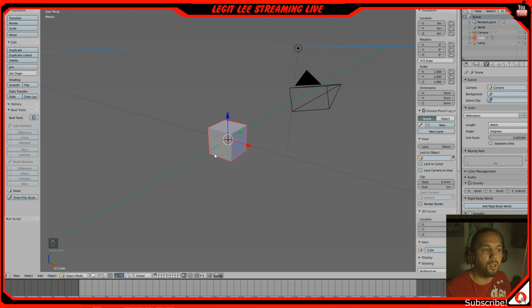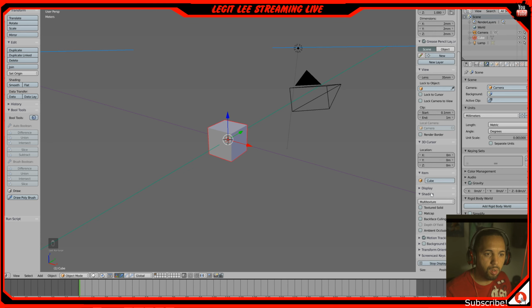But we have to set up how we can see our grid line, because we're super zoomed in here. So what we're gonna do is go to our display. If you just scroll down here on the end panel, you have scale. You want to scale this to be real world. So you just basically are copying this number 0.001. So we're going to do this really quick here. Now you can see we're in the same exact display as everything else, and our grid lines is 16 millimeters squared. Each square is 1 millimeter exactly.